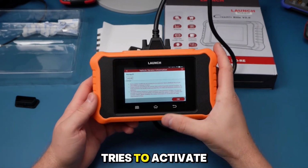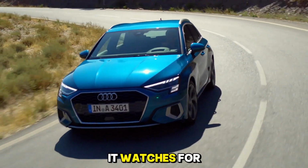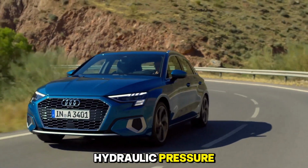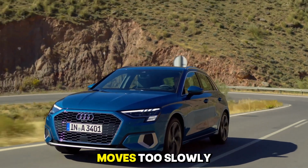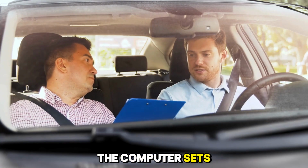When the computer tries to activate solenoid J to shift a gear or adjust line pressure, it watches for a specific change in the electrical circuit or the resulting hydraulic pressure. If the solenoid gets stuck, moves too slowly, or the electrical circuit behaves erratically, the computer sets this code.